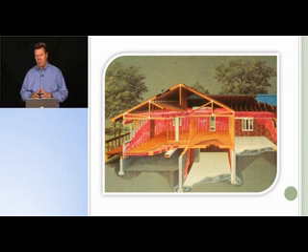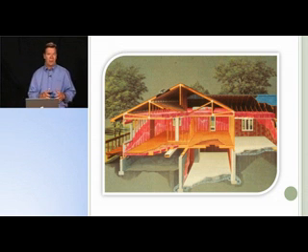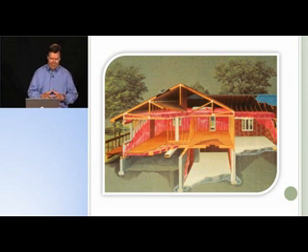Another important concept to understand for energy basics is what we call the thermal envelope. That's essentially where we're defining the difference between indoors and outdoors, between what we call conditioned space, where we have to condition the air, whether we have to heat it or air condition it, and the outdoor space, which is what we call unconditioned space.